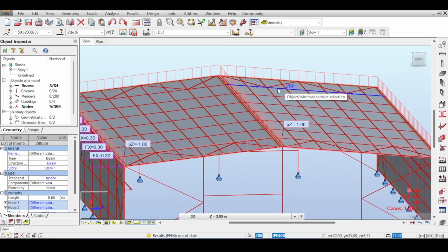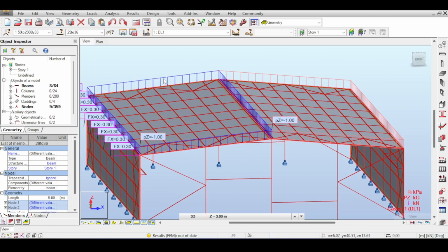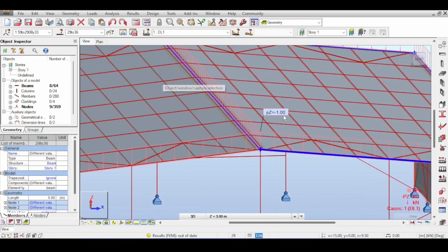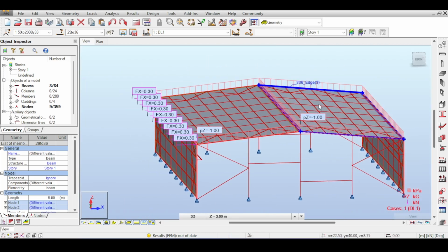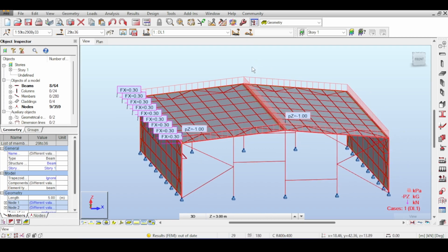You have to have accurate dead loads, because dead loads, in the case of uplift, are actually a good thing, because the more dead load you have, the more resistant to uplift your structure is. So oversizing my dead load to 1 is something I have done in the last video. It was 0.6 and I put it 1, and I just wanted to mention that you need to be more accurate than that. Of course, here I'm just explaining everything and hope that you choose the correct decisions that you see fit.